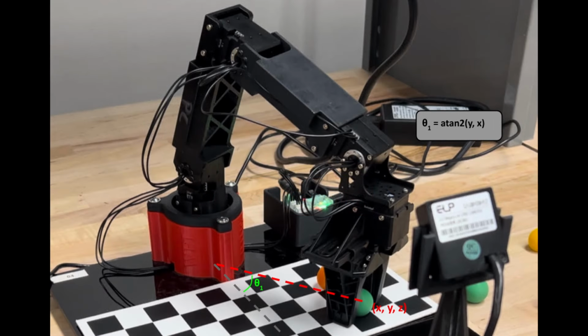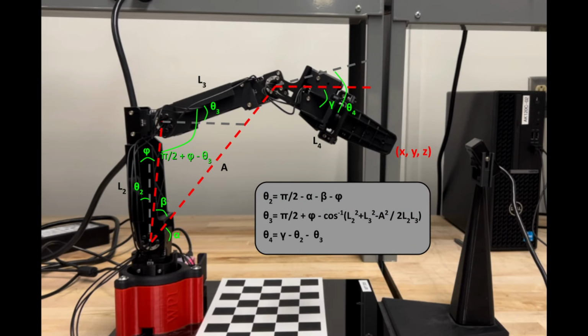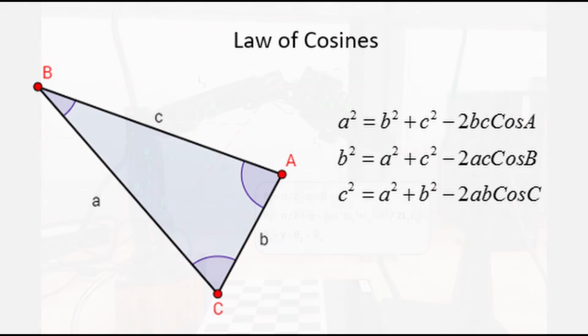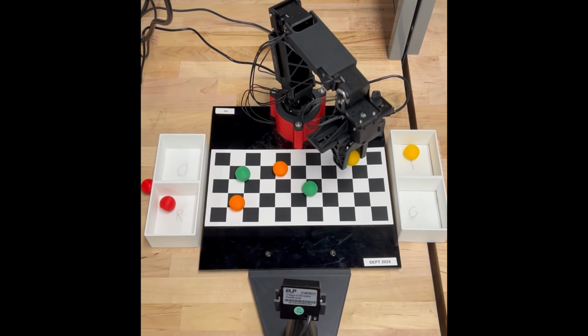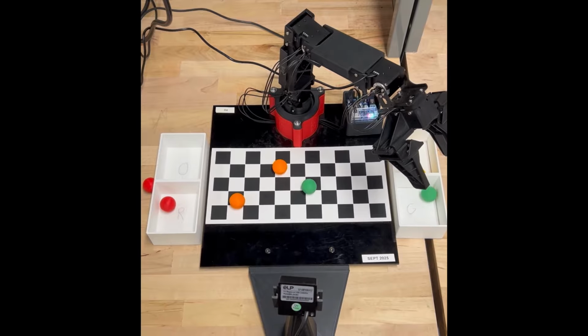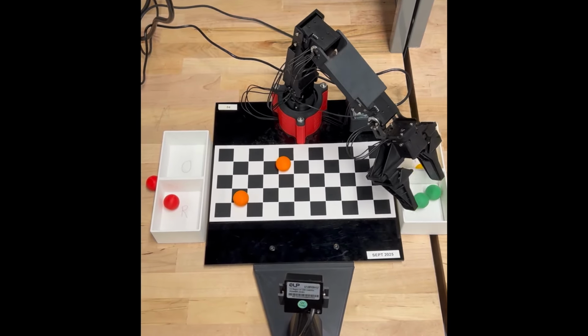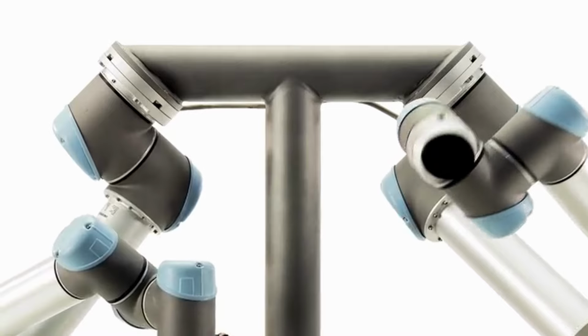When it comes to calculating the inverse kinematics of a robot, we were able to explore both analytical and numerical approaches. Analytically, we use the robot's geometry to draw the various robot links in different planes and use the law of cosines to solve for the angles. An important thing to note is that we have 4 degrees of freedom for this particular robot arm, but only need 3 to reach a target position. To prevent infinite solutions, we had to create an extra orientation parameter, which is the angle of the robot's end effector with respect to the horizontal plane.